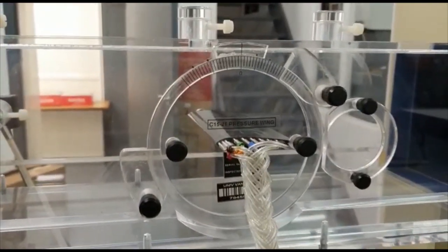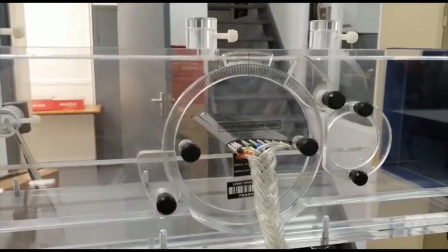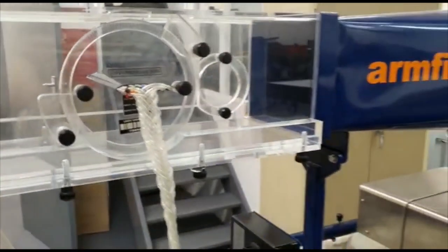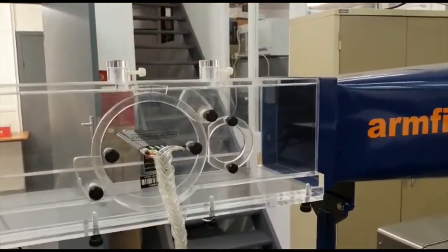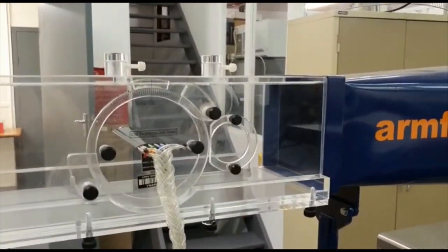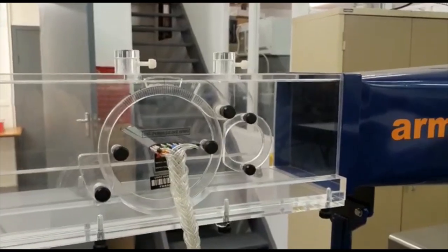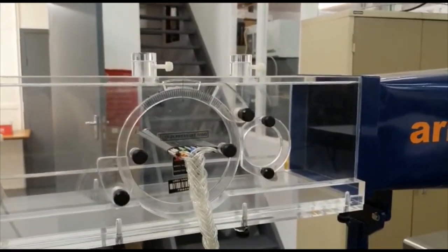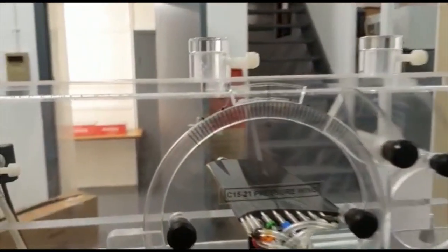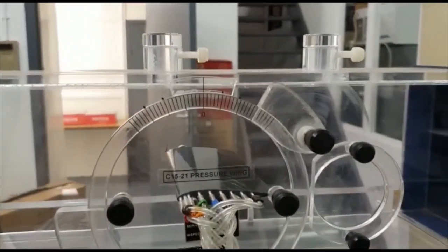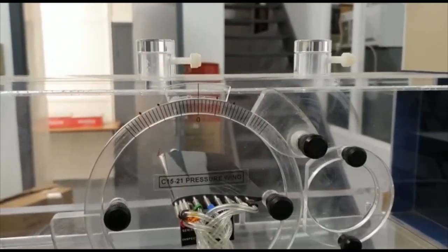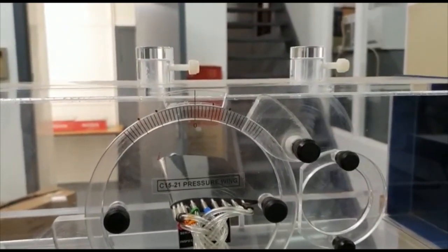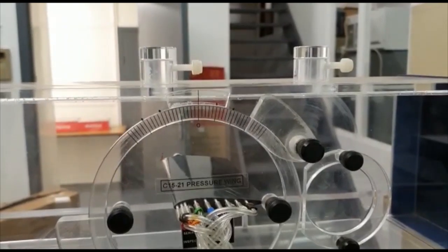So the process here is getting the information in volts, then making sure they are translated to pressure, and then dynamic and static pressure is used to calculate the pressure coefficient, from which you can compare these different angles. If you look closely, there's an angle of attack meter here at the top, so that is something that the teaching assistant will change, and it's currently standing at 0, and so every time you change an angle you're changing it around that meter.